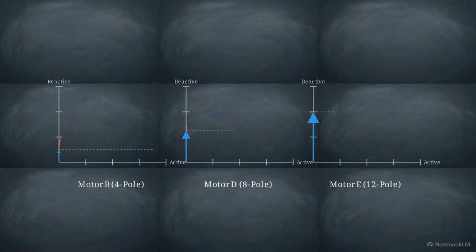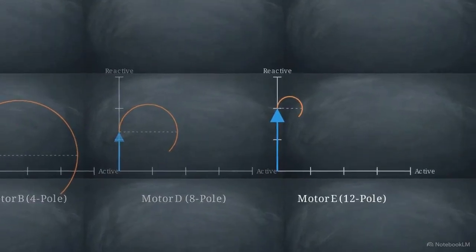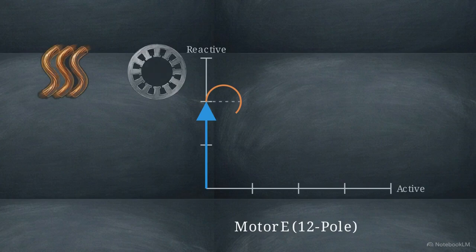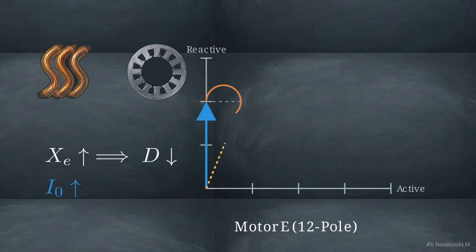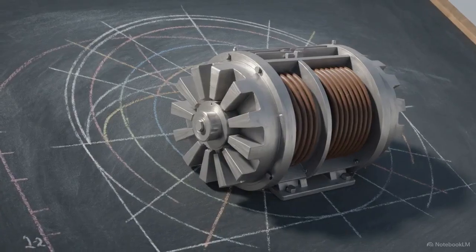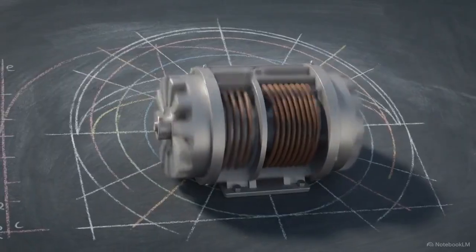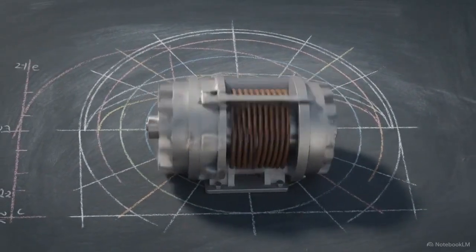In low-speed motors, the reactive magnetizing vector stretches higher on the axis at the exact same moment the overall performance circle is shrinking. This warped ratio between magnetizing current and circle diameter significantly impacts efficiency. Because the origin point sits so high relative to the tiny circle, drawing a tangent line strikes the outer edge at a severely flattened angle. The poor power factor found in low-speed induction motors is an inescapable geometric consequence of magnetic design, perfectly visible in the Heyland diagram.